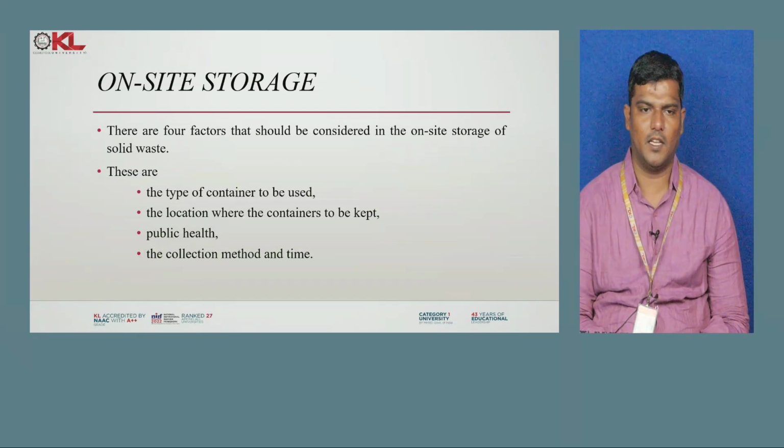Next one is public health. If you are storing outside on the street, generally flies will come, which will damage the health of the public. And the next one is the collection method and time, like how frequently we are collecting the waste, as well as how much time we will be taking for it. So these are the four key factors which will be considered for on-site storage of solid waste, which we have to keep in a regular manner.